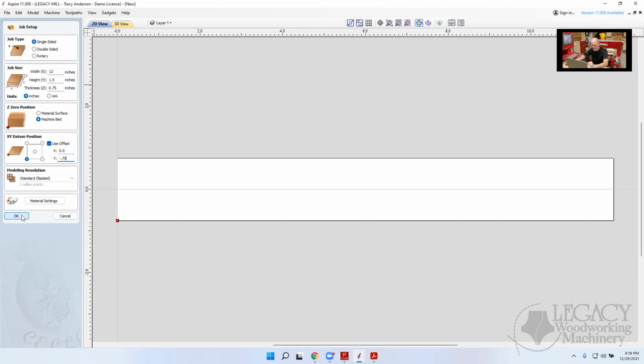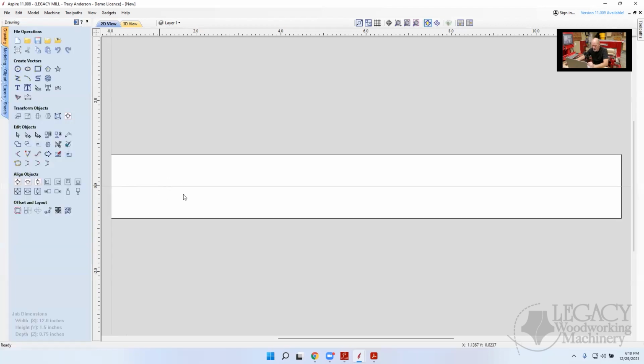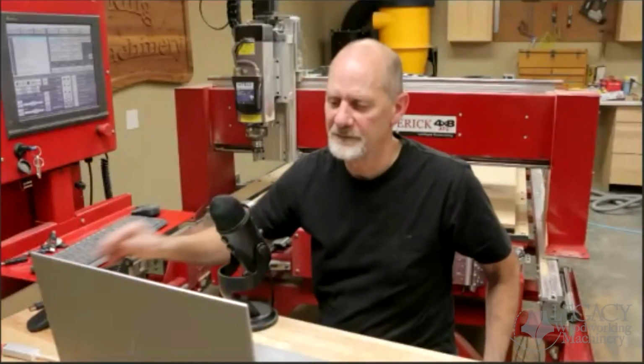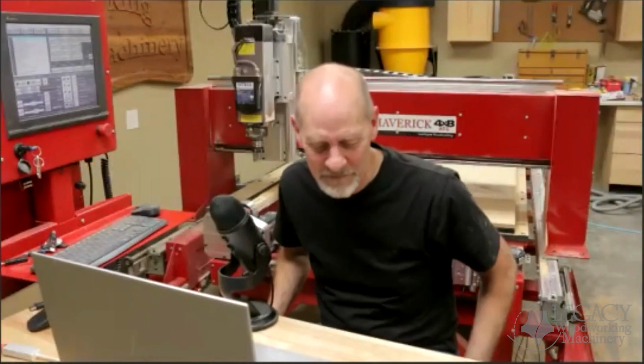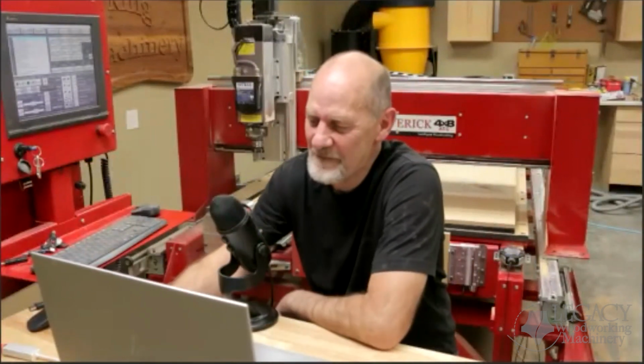If you set it up this way, then any code that you generate to cut on here, when you load it into the system and touch off the Smart Tool, it's going to set the Y0 to 0 right along here, the X-axis right here at this end, and the Z-axis will be measured from the center of the blank, taken from the Smart Tool touch off. Yeah, that's how I did it. Perfect. All right, good deal. I'm looking forward to seeing how it works out for you.